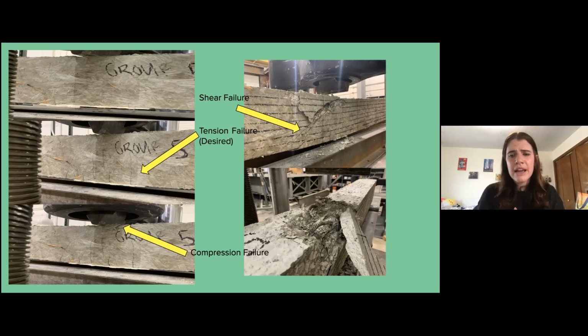Then over on the right, you can see that I also mentioned shear failure. With this, besides having the concrete, having those rows of steel on top and bottom, earlier, as you saw in the cage, we also have steel that was put every other 6 inches across the beam. This was to prevent shear failure, so it hitting kind of sideways. And this awesome one that you can see is from that shear failure. So we ultimately did get that as well.